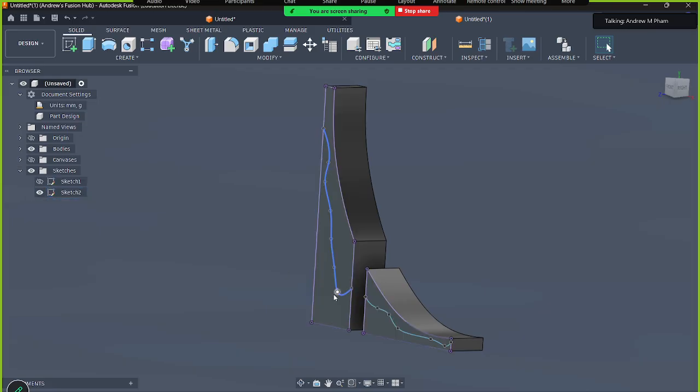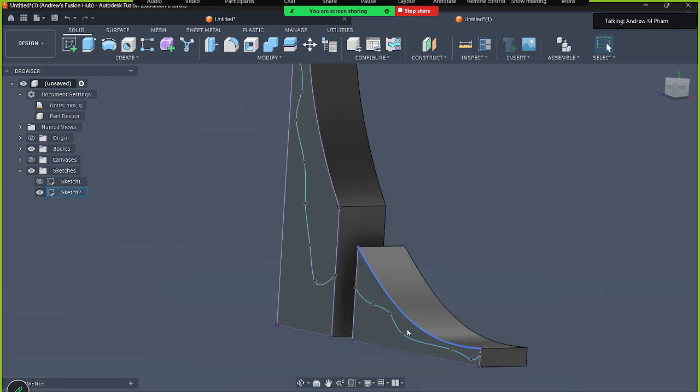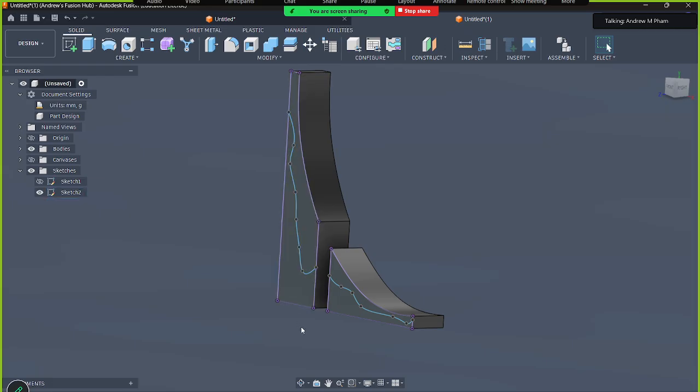For the sketches, you should be able to highlight the individual areas because that signifies that they're closed bodies. If it's not for some reason, then it might be because one of your 2 endpoints may be either close to the edge but not quite, or not there at all. So you want to make sure you have some kind of endpoint on your projected lines. You can use the coincident function. Once you do that and these are highlightable, you want to exit the sketch.